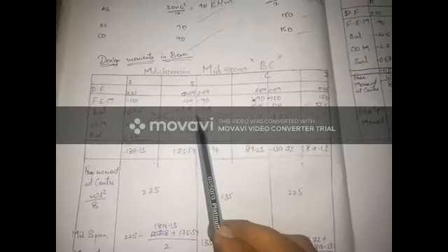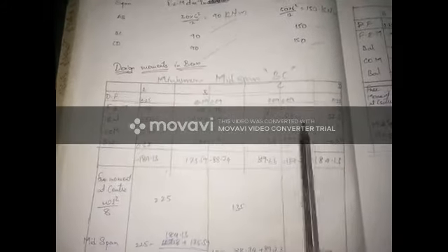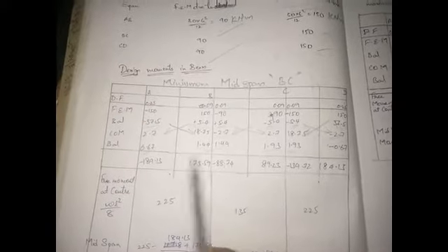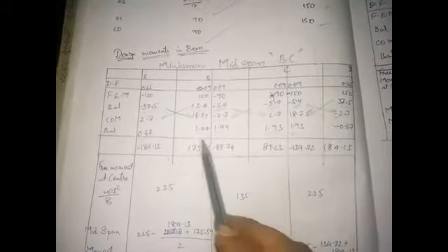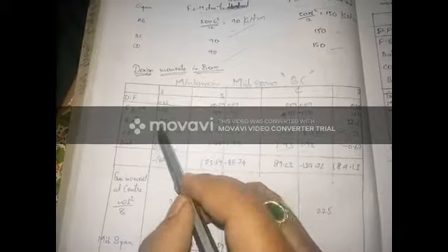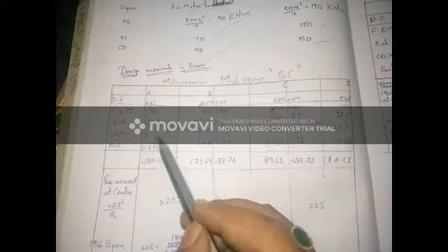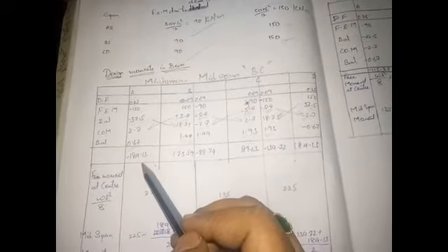If we repeat the process, the section is already balanced here itself, but for the cyclic process a carryover moment should happen in the section. So if we want to close the problem, we need not go for carryover moments. So we have closed it here itself and have taken the values. Now we will take the sum of values as minus 150 minus 37.5 plus 2.7 plus 0.67, that is minus 184.13.